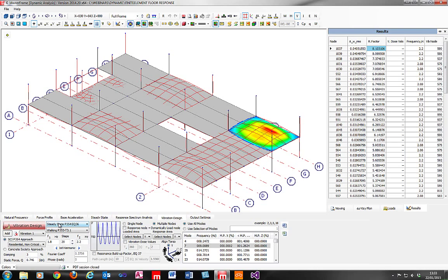You end up getting what's called an impulse type of vibration as a heel might strike a floor, and you would get a series of these impulses. Now that doesn't lend itself to a steady state situation, but what's called a transient situation. You get a higher peak acceleration at the heel strike, which then dissipates out to a much lower steady state. So therefore the transient situation actually causes higher peak accelerations and therefore larger response factors.